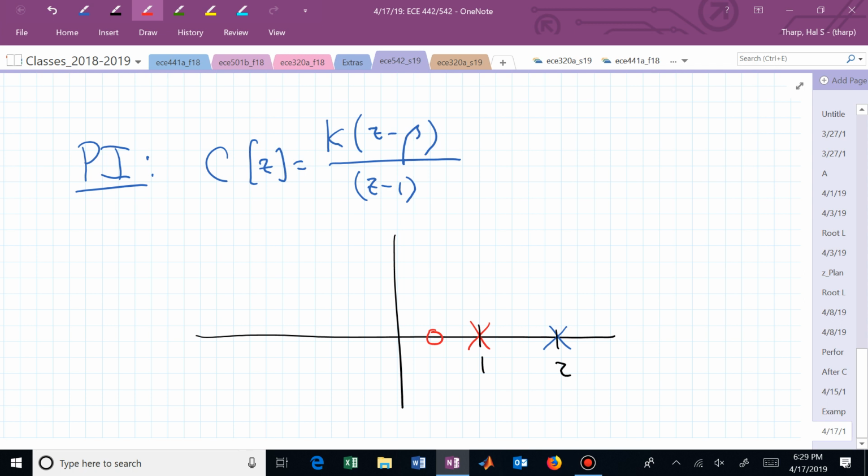with what? Our root locus branches by the choice of a 0. And now we know, I kept talking about 2 poles and a 0, but this is why. Now you can immediately draw this picture and say, if I locate that 0 effectively, I can swing those branches of my root locus inside the unit circle.